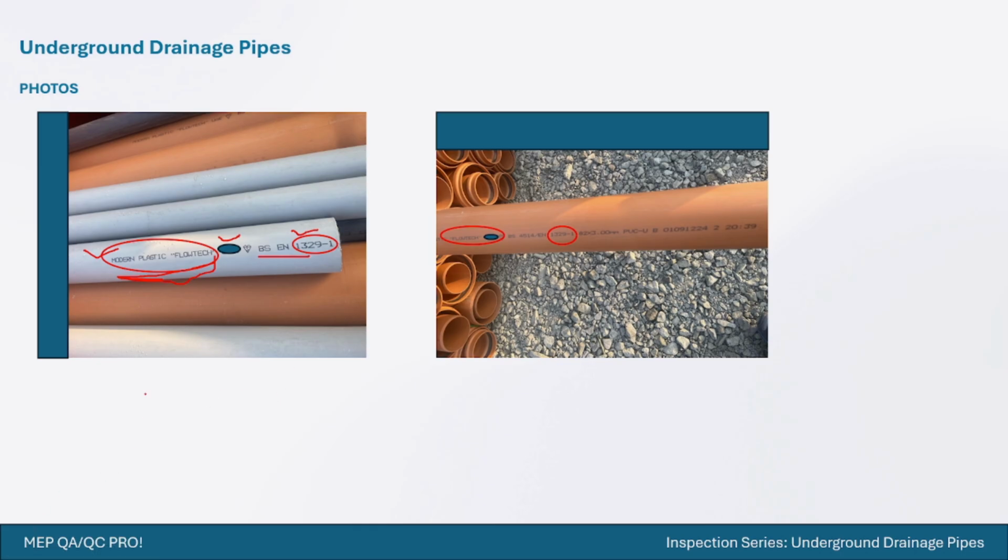So this is all about the material inspection done internally with your site team and by yourself. You should have knowledge of which brand, which standard, and which country of origin the material comes from. Once this is fully completed and you are satisfied that the product delivered at site meets our site requirement, then you go and submit your material inspection.